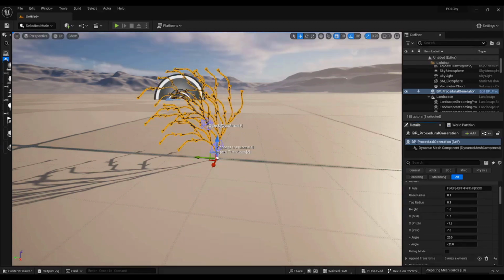This tool uses the L system that takes in a user's input of strings and allows the user to control multiple transform points in three-dimensional space and generating an output mesh in real time. This tool utilizes transform points from where the mesh generation takes place and moves these transform points along the up vector. As I delete the string input and hit enter, you will notice that the mesh updates in real time within the viewport.